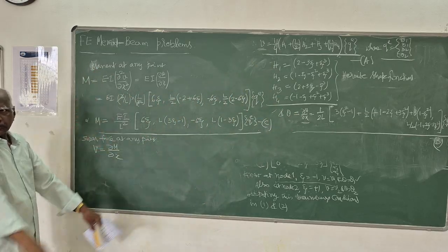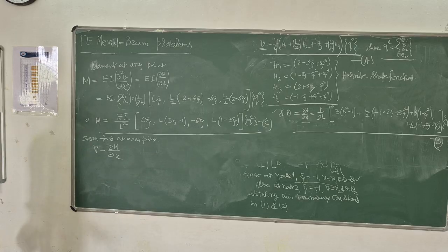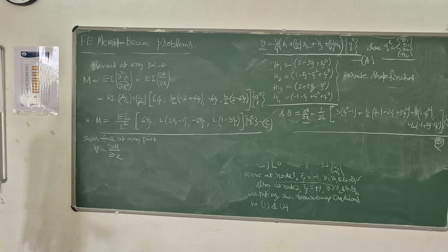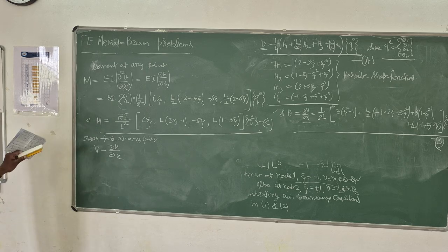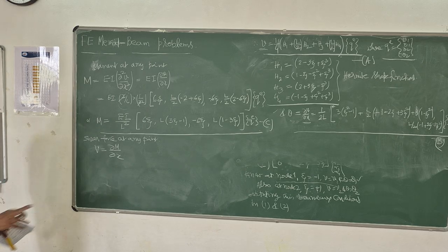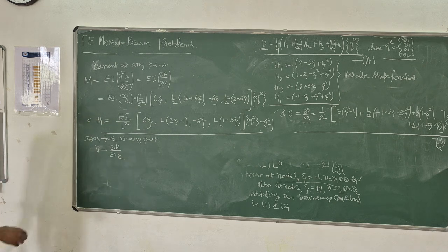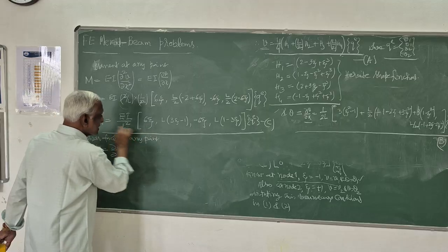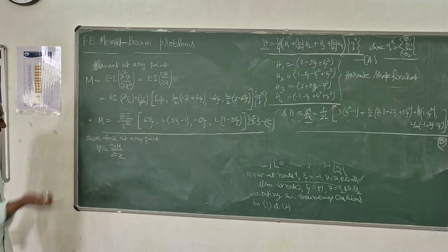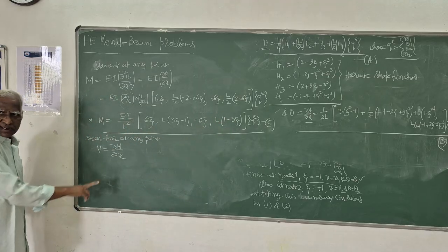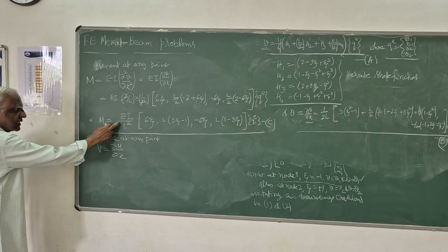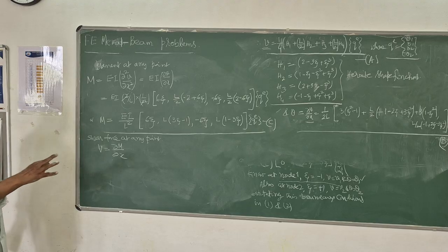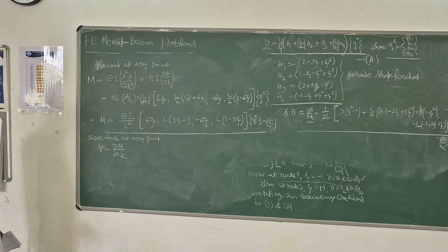Displacement, actually, you have to derive from the first principle of the finite element method. Assume it in polynomial form, get it. So this much procedure is there. Finally, you have to remember these things. And V is nothing but delta M by delta X. Again, this M is a function of Z. We are differentiating with respect to X, so we have to multiply this by the Jacobian inverse. That is the transformation matrix which I told you about for isoparametric elements.